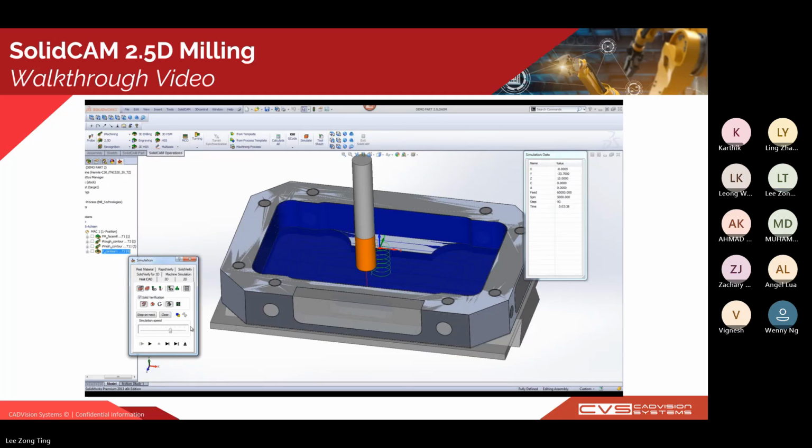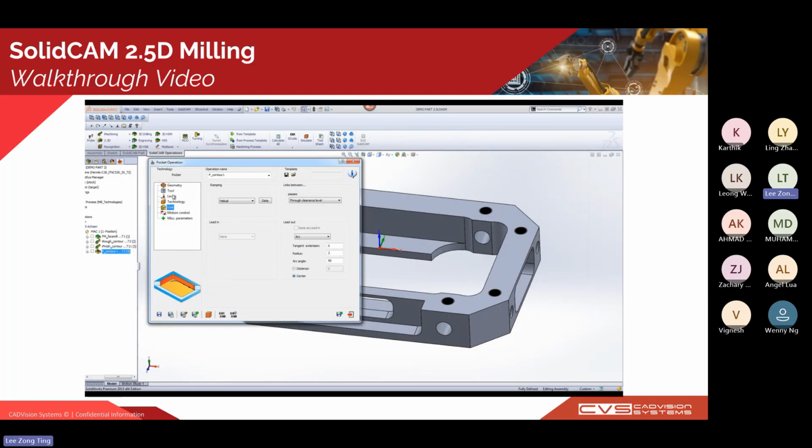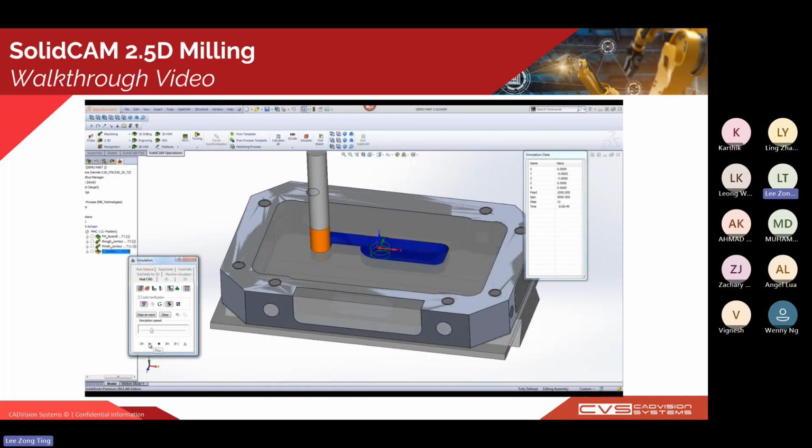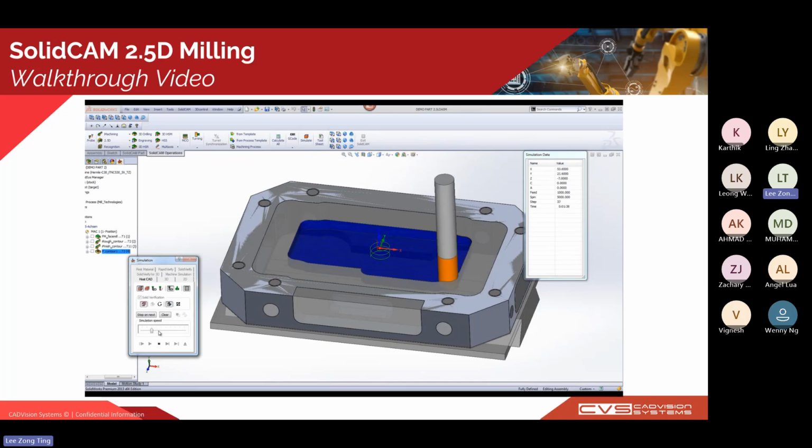But after that, if you have anything you want to change within these operations, you can directly go back to these operations. For example, I want to change the step down. I don't want the tool to go too deep the first time. So I will change my step down to 7, and you can see how easily it is able to recalculate the toolpath and give me a new toolpath.